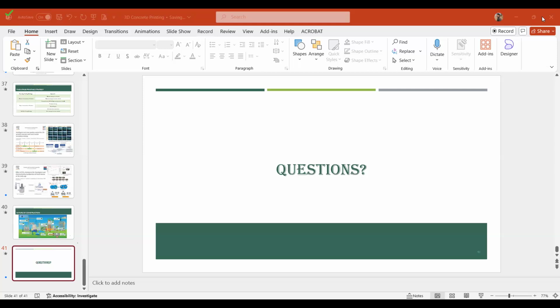Okay, the second question written in the chat box is, can we make some building to be used commercially, and is there a comparison of the cost? Again, it's the same question. Commercial buildings are made, and houses are made, and houses are cost effective as well. In different countries the process is different. In USA or in Europe, there are different companies which not only prepare 3D printing concrete, they also prepare the cement which is used for it. Mostly the companies claim that the cement they are using is eco-friendly. It is not that they are using a lot of cement; they use a lot of supplementary cementitious material like fly ash and slag, and it is quite economical as well.